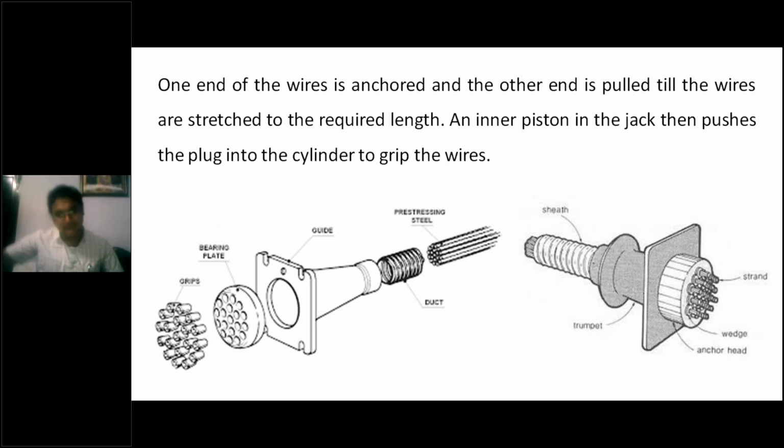Okay, and the inner position is then the jack then pushes the plug into the cylinder to grip the wire. So this is the system, Amma. Just you are going to pull the strands, then the concrete is going to be squeezed with the help of the compression forces.